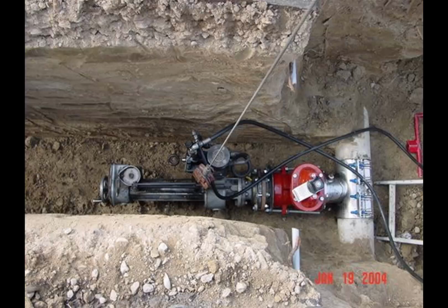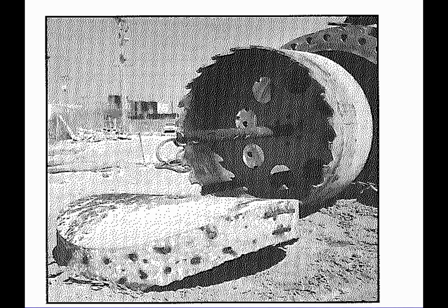The drilling machine is attached to the valve. So once again, with the valve open, the bolted assembly creates a seal, so you're not leaking any water once you make the cut. The machine pushes the cutting head and cuts a hole in the existing pipe. Then it pulls back out and actually pulls the material that it cut out with it. That's called a coupon. And then you close the valve and you have a brand new connection.